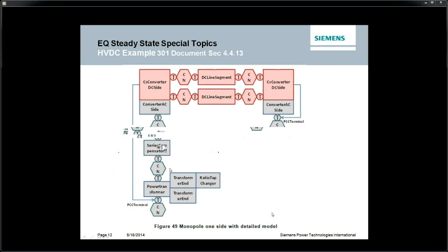As a footnote, within the short circuit data, all of the positive sequence reactances on the synchronous machines are considered to be saturated values for short circuit. And that's a footnote because if people are used to also working in dynamics, that data has to be replaced with dynamics data for unsaturated values for dynamic simulation.